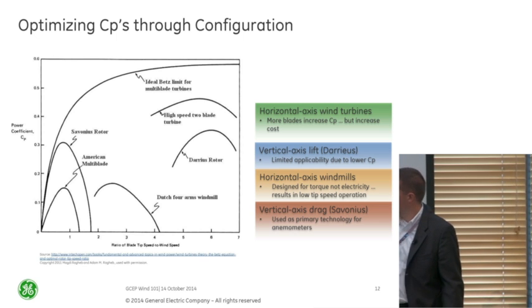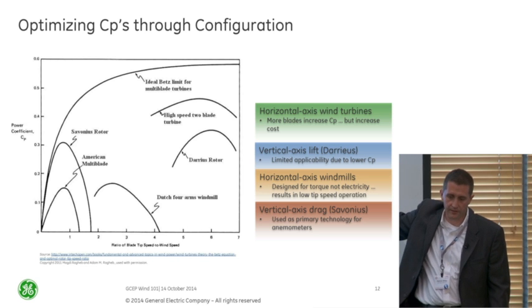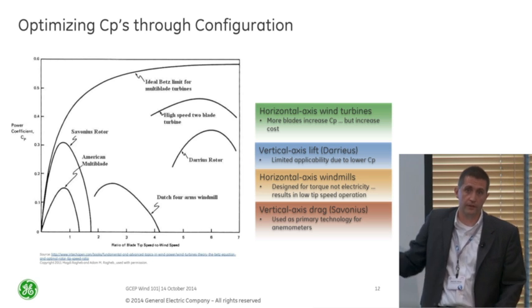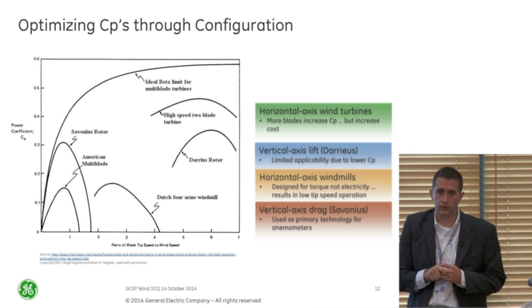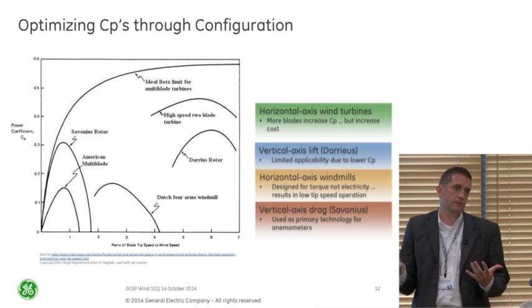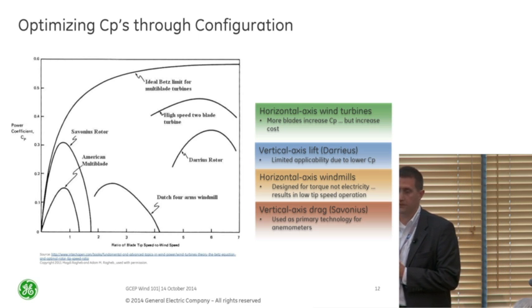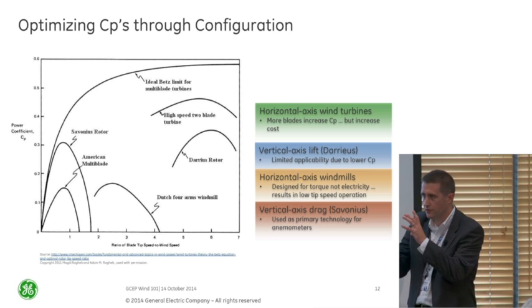You know, that Savonius rotor, I don't know if I believe the peak of this. Actually, I think the peak of it should be a lot lower. I think most of the Savonius rotors that are out there are only around 15% on the CP. They're typically only used for measurement of wind, which is really good for doing that. So you see them as the way we typically measure wind on top of a wind turbine. You'll see this little thing spinning if you get really, really close.